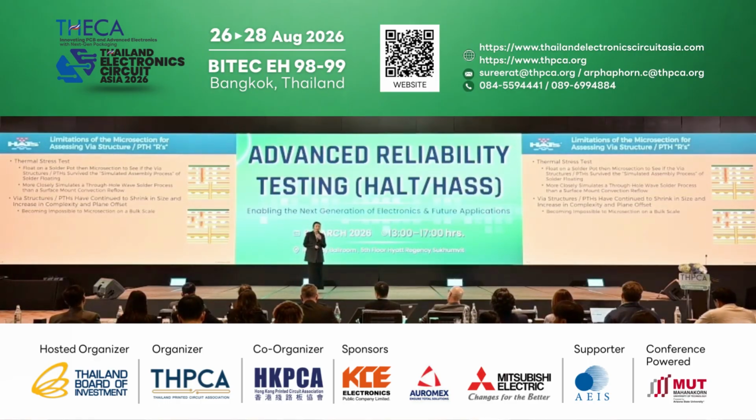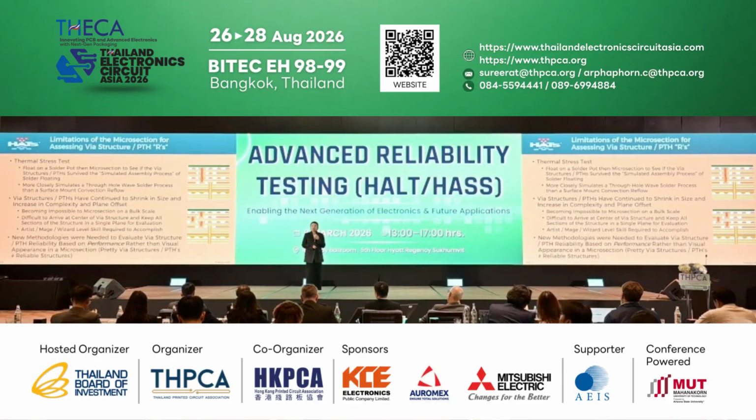And as we all know, the via structures and the PTH these days have continued to shrink in size and increase in complexity, which means it's almost impossible to microsection in bulk scale. You cannot microsection 1,000 or even 500 in one day.